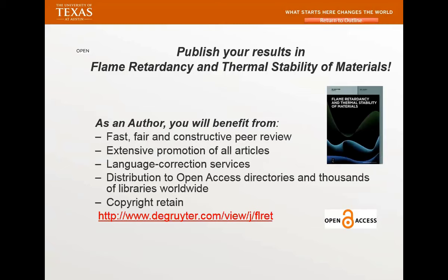That's what I learned from carbon nanofibers in applied science. When they came up with all these carbon nanofibers, they were all flexible hairballs. If you try to bring them into your thermoset, it's tough. You have to debulk it. You're not going to beat it to death, getting very short fibers. Then you may have to do some experiments to see how it works. I think pre-processing works a lot better than going directly. Okay? That's kind of what I do. Thank you. Any other questions?